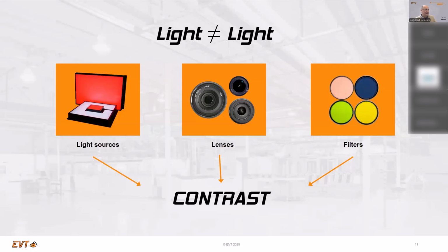We always support all these camera manufacturers, and of course you can connect, depending on the interface you use, any of these cameras to the software. A lot of people buy a 20 megapixel camera and then buy a lens, and they tell us, look, especially for the measurement, we cannot reach the calculated accuracy. And then finally, we find out at that point, yes, they have a 20 megapixel camera, but they have a 5 megapixel corrected lens.